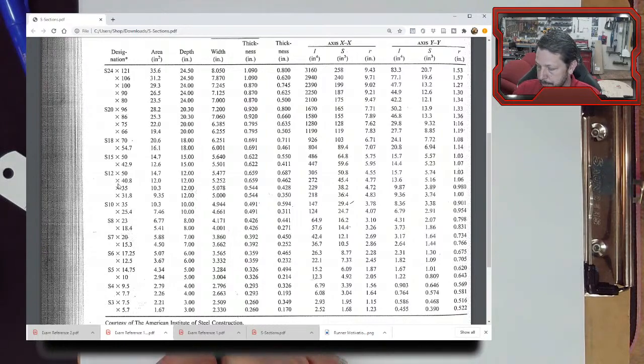So you usually have to pair these calculations with flexural stress calculations to be sure that the beam actually can survive whatever we're causing it to bend into, because these equations don't tell you anything about flexural stress. They just tell you, assuming the beam doesn't yield, here's what will happen.